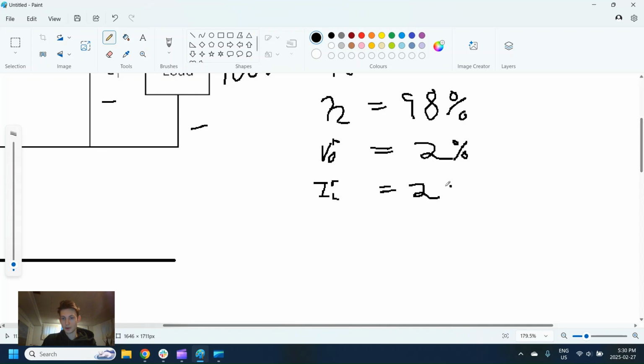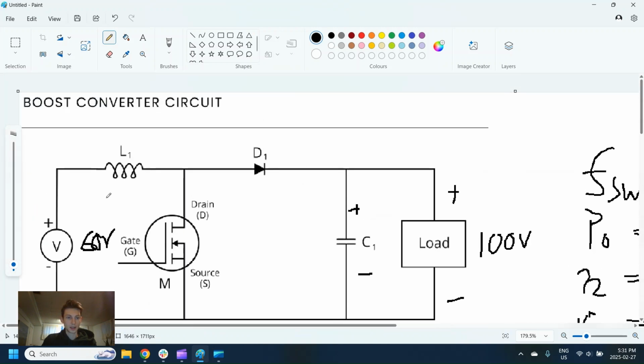And this is normal. Even higher could be normal, as long as the current doesn't go below the x-axis. So if this is the positive current here, as long as the current stays above it, it can ripple a lot, and we don't really care. Higher allowable ripple means we can use a smaller inductor because it doesn't have to store as much energy between each cycle. But it causes problems elsewhere, so we'll stick with 20%.